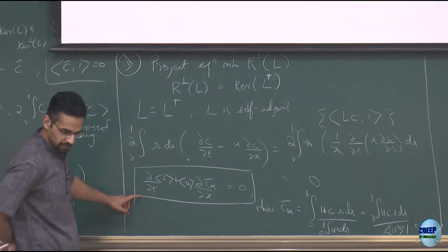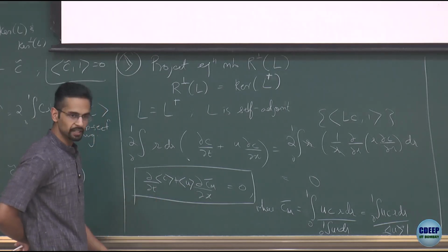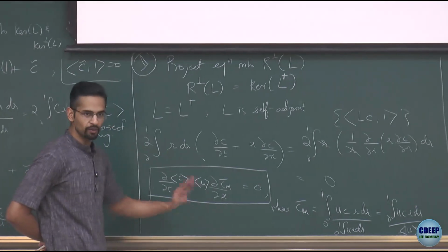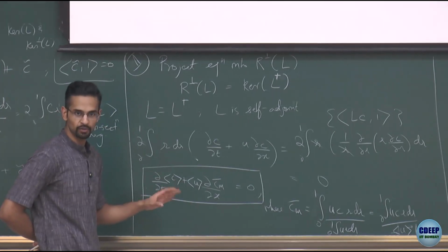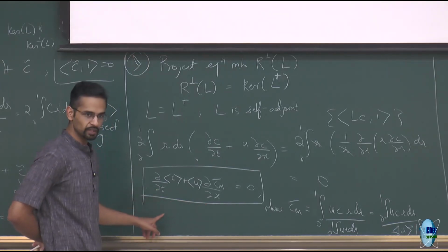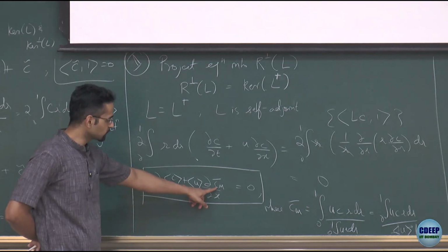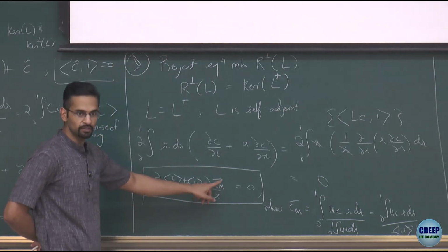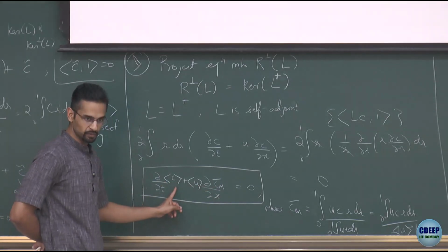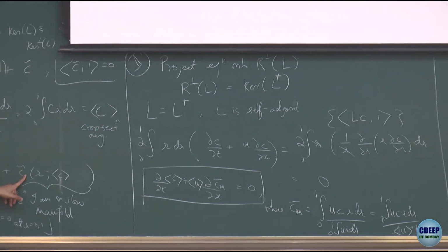Okay, so we have reached a point now where we have some kind of one-dimensional advection equation, right? Because remember, we threw away diffusion in x because it was r square by L. So in the x direction, all that remained was advection. You would of course have time. So we have some kind of pure advection equation. The catch is that you don't have C average here, you have this cup mixing average. So I need to know what is the cup mixing average in terms of C bar. That's just another fancy way of saying I need to know C tilde.